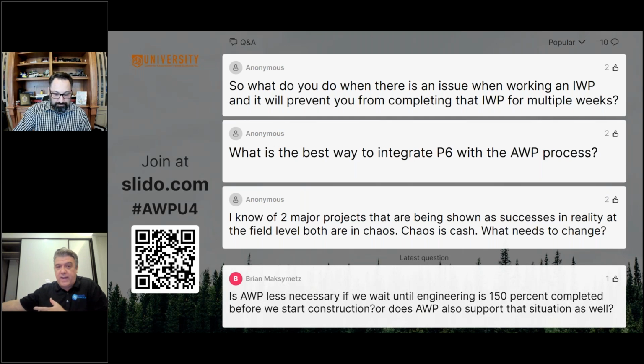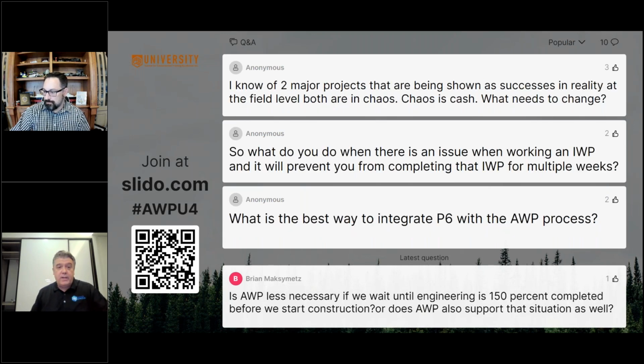If you've got the laydown area material, and even if you don't have the laydown area, you should have the IWP ready to get the materials out, so the crews can shift to something that's not constrained, because one IWP may depend upon that IWP. So have something that doesn't depend upon that localized sequence ready to go where a crew can shift during the week. But then at that point, the answer really becomes you have to analyze what the situation is and replan. And it may be, remove the scope that's not able to be completed and repackage it. Or it may be, hey, I'm just going to put it on hold for 2 weeks and complete it.